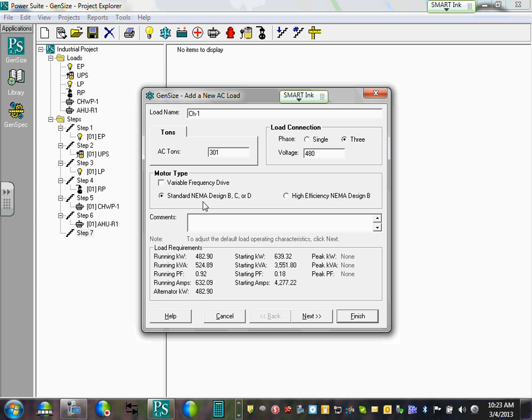Most likely, guys, if it says chiller division 15, I will put a VFD on it though. On the chiller, 99% of the time we'll have a VFD, and pulse width modulation. I know it's not saying it there, it says by others. Put a VFD on it. Pulse width modulation, 480, 3-phase, everybody's there? It changed my kVA. Running kVA 550.